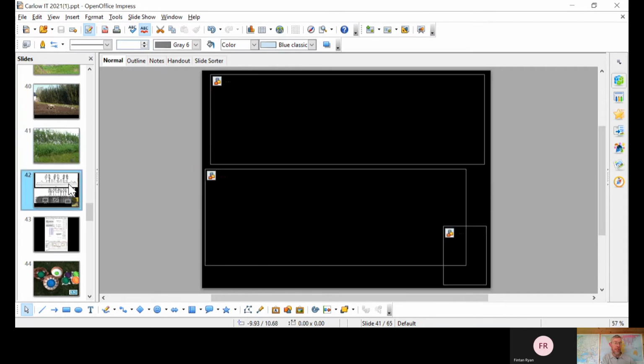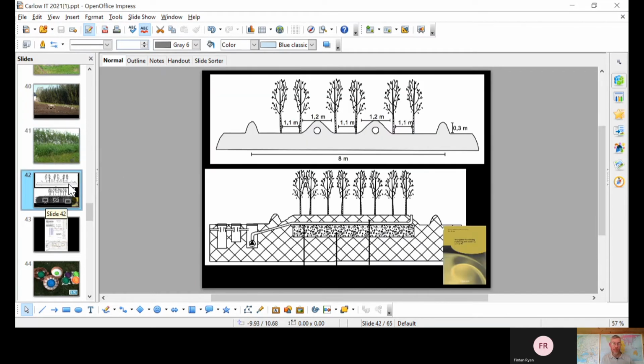Now, something that's more cost effective and, to my mind, a lower resource input is the Danish design guidance for unlined willow basins. And it's basically the same general idea. You've got 2 spreading lines rather than 1, and then your willows are spread out in a bunded basin, but there's no liner underneath the base. And Denmark generally has very sandy soils, and this is one of the methods that they use to mop up nitrates and phosphates en route into the groundwater through those sandy soils.